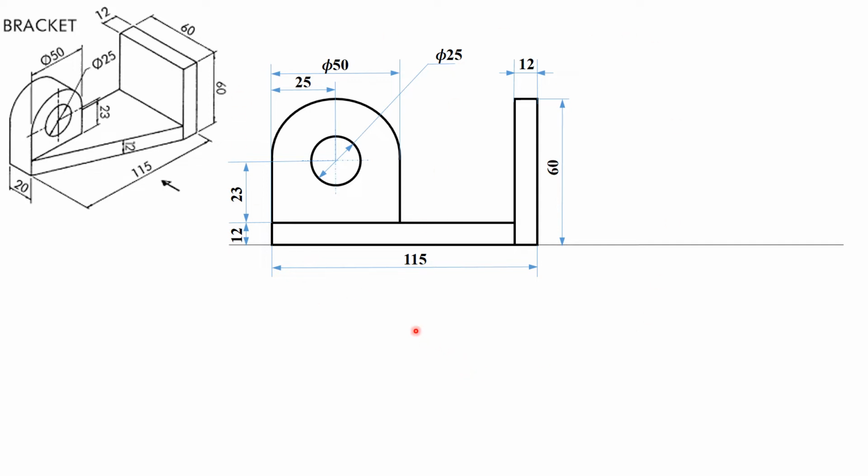Now let us go to the top view. To get the top view, project all your available edges onto the top view side here. Similarly, please also project the ends or extremes of your circles, as that will mark the boundaries of the circle. If you project these lines, you will be able to get the top view of the cylinder. The hole here we can assume to be like a cylinder of this much diameter and this much length. Here the length is 20 mm.